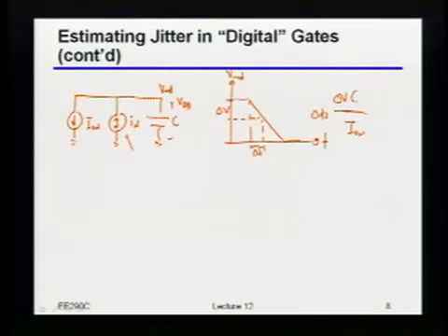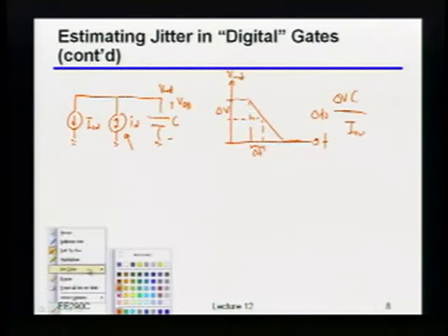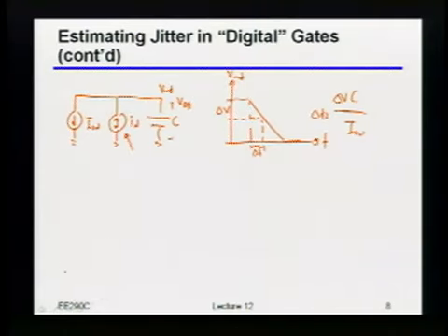Because I've got a white noise current, but I'm dumping that noise current into a capacitor, right? So what I'm actually looking at is the voltage now. So what is that sort of doing? 1 over F. Okay, you said 1 over F. It's actually 1 over F squared. Although even that's not entirely true, because I'm basically integrating that noise current. Right, what I'm basically doing is integrating this noise current over a window of time, right?